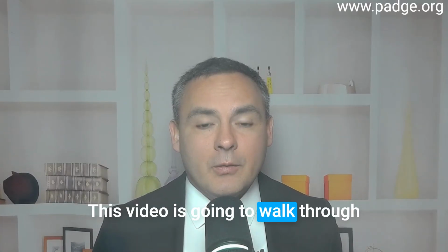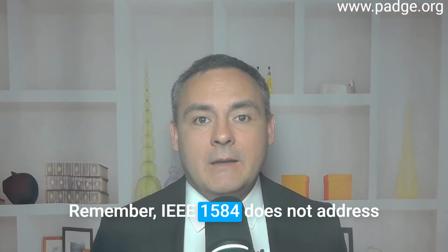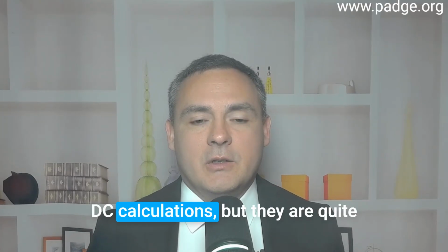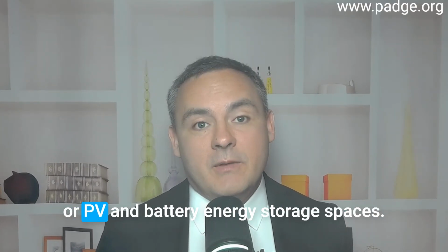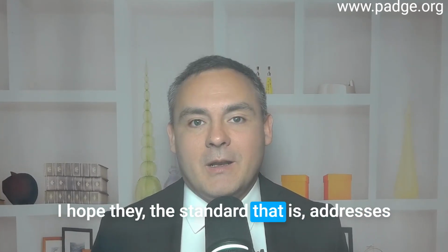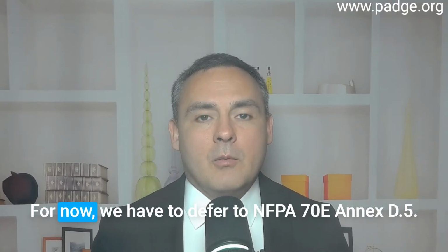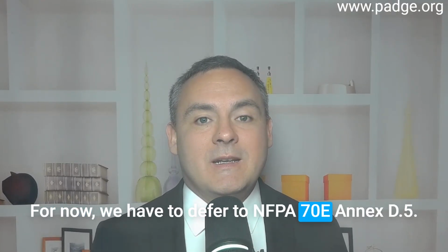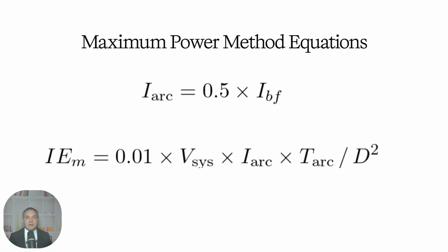This video is going to walk through an example for a DC arc flash. Remember, IEEE 1584 does not address DC calculations, but they are quite important, especially in the photovoltaic or PV and battery energy storage spaces. I hope the standard addresses this in future editions of IEEE 1584. For now, we have to defer to NFPA 70E Annex D5. That annex provides the governing equations that are known as the maximum power method.